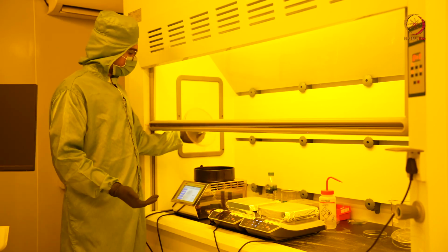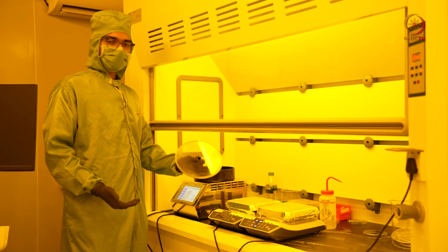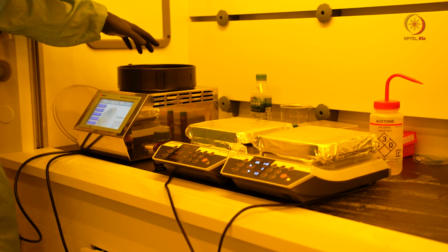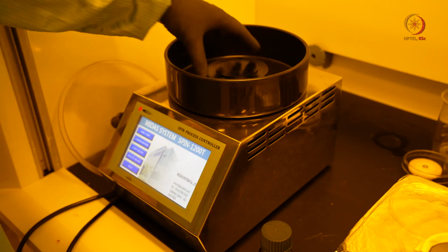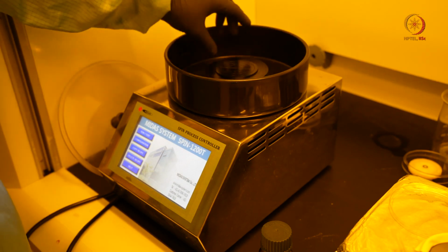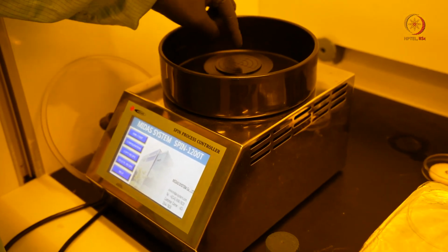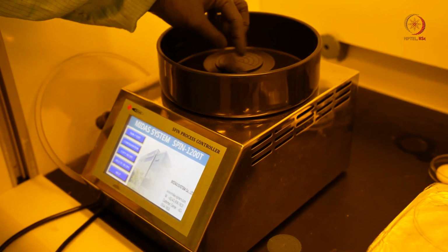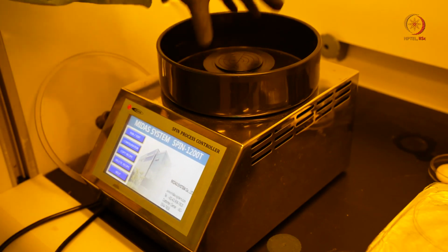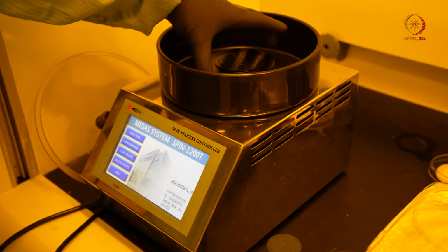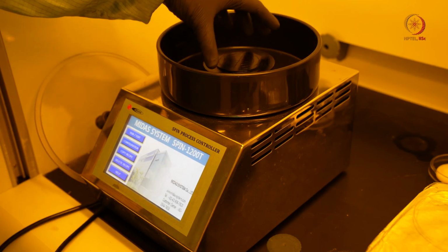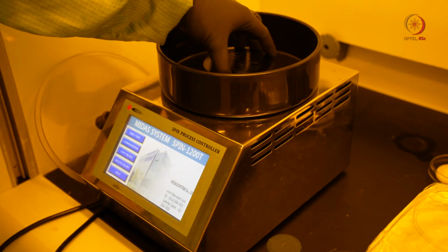Okay. So this is the lid of the spin coater, which I'm keeping here, and this is where we load the sample. Now you can see that there is a chuck. This is known as the chuck, which is able to rotate, right? And you can see a few circular grooves here with a center hole. Now the point of the chuck is that when we load the wafer onto the circular chuck, through vacuum suction the sample will be held here.